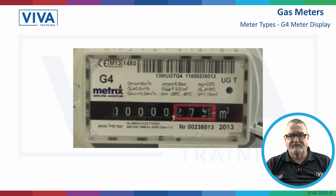So if we look at the display now, what you can see there highlighted in red, that is the test index. Before that, you've got the billing index. So the 5 numbers before where the comma is, that's what's used to bill the customer. The ones highlighted in red, they're the ones that we use when we're measuring things like gas rates. We're going to be looking at that in a later presentation, understanding gas rates and how to measure gas rates.